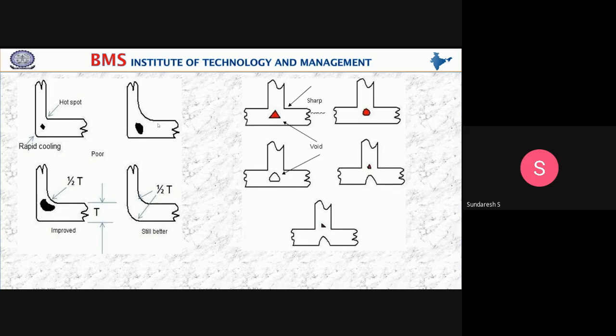So when you are designing any component, be careful while you are giving the corner angles or corner radius. The inner radius should be as large as possible, so that you can minimize this kind of hotspot.